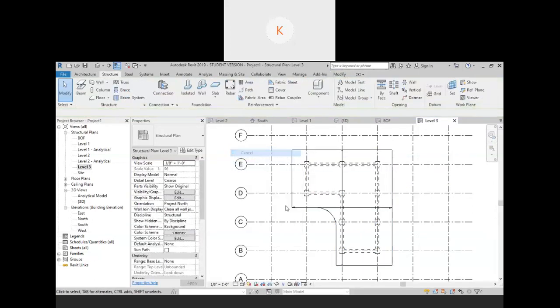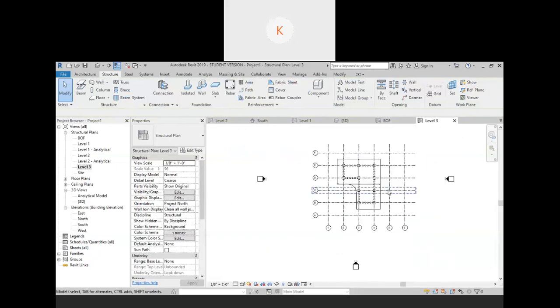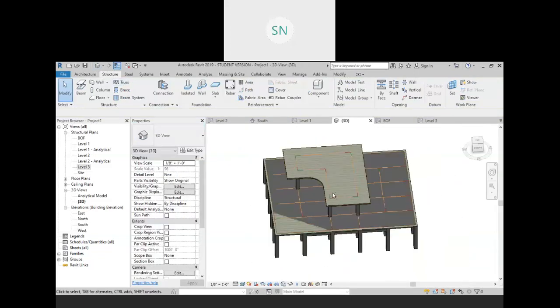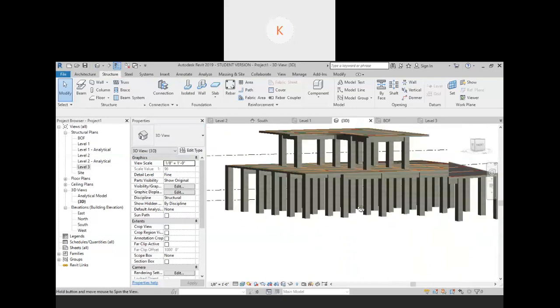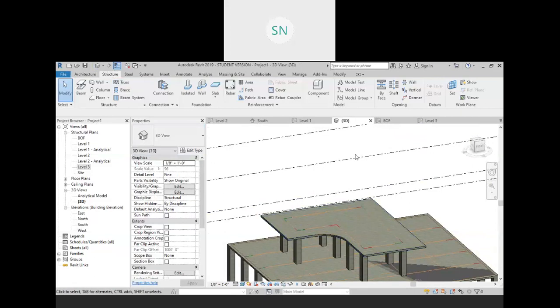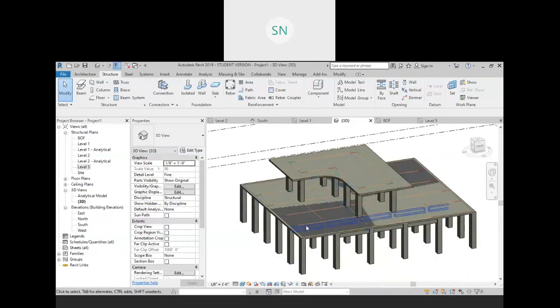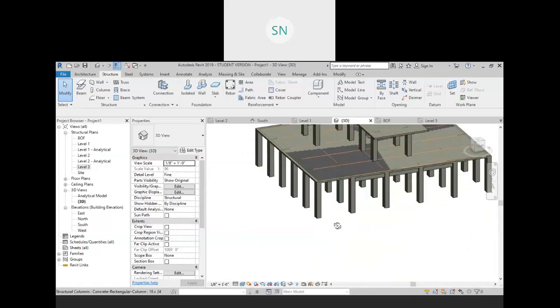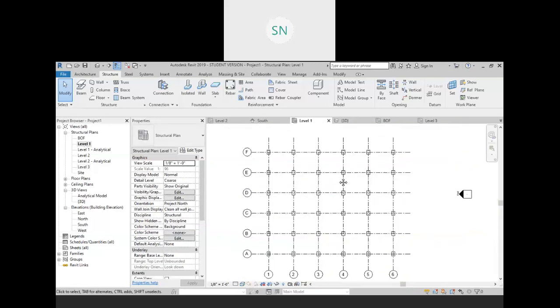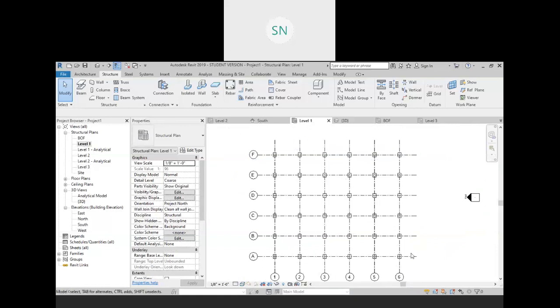And this is my next structure. And if you want to continue further, you can, right? So you just need to extend this column further, and you can start your work over there. Now let me create some structural walls. So the creation of wall is also very important in this. So for that we are going to level one, and for example I want to create the boundary for these two sides only, right? So we'll create a wall for two sides only.